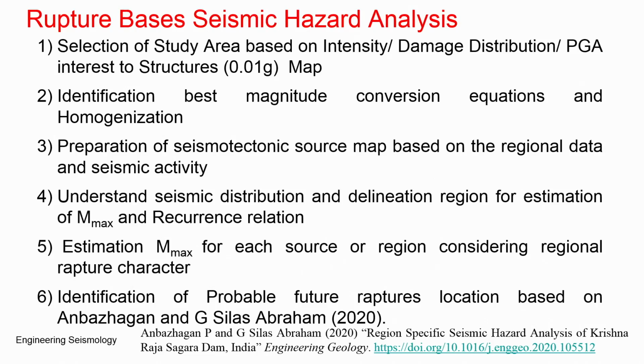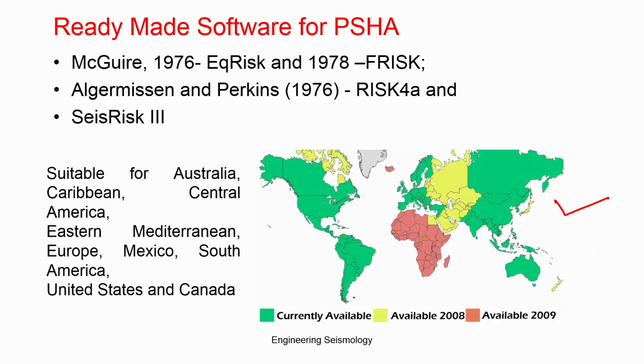Even though these models are available, you can see that DSHA and PSHA don't really account for regional variation, because they didn't specify what seismic study area you should take, which we have seen is very important. They didn't specify what Mmax you should take, or what GMPEs you should take and how to take them. Generally they are given as global, so you can adopt anything.